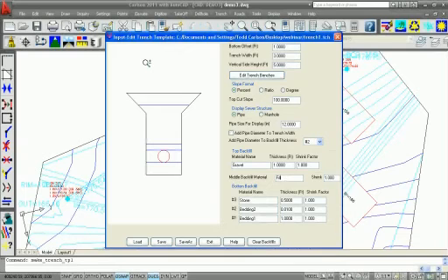Right, yeah. So what this is going to do is give us complete volumes for the stone, bedding, and gravel that we've defined here, a lot more sophisticated than just looking at the plan and estimating by the distance of the pipe, because the depth of the pipe is changing, so some of these materials are going to change depending on the depth and the width of the pipe. I know some of the users have informed me that, as we've all learned in this industry, the cost of doing site work is how many trucks need to go in and how many trucks need to go out, and hopefully we don't have to move too much material. But they also like the fact that they can add in the subgrade materials and calculate that cost-related factor at the same time. That makes it a lot easier for them in billing the job, if you will.